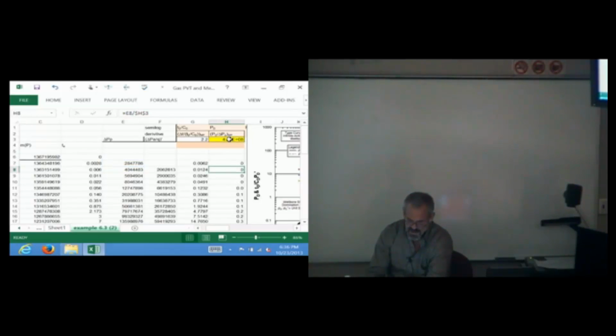And the reason we do that is because people like numbers bigger than 1. They like match points bigger than 1. And since it doesn't matter if it's oil and I'm using pressure, or if I'm using gas and using pseudo pressure, my delta P's and my delta pseudo pressures are large numbers. In order to get them into the dimensionless time range, I have to divide by a big number. Otherwise, I'd be multiplying by 0.000 something.